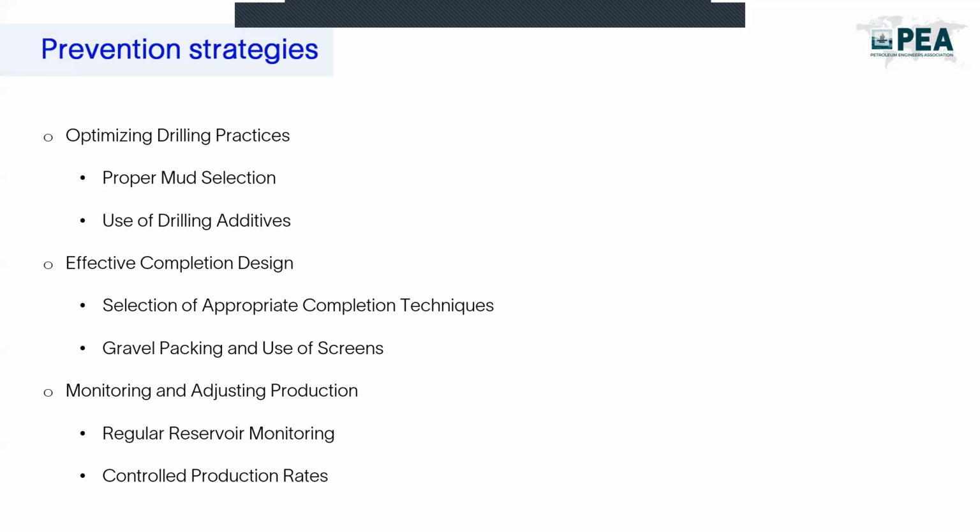Now we move on to the other one, which is having an effective completion design. Obviously, selecting the appropriate completion techniques. The design of the well completion must minimize the potential for formation damage while maximizing the hydrocarbon recovery. For example, choosing between open hole and cased hole completions based on the formation characteristics.